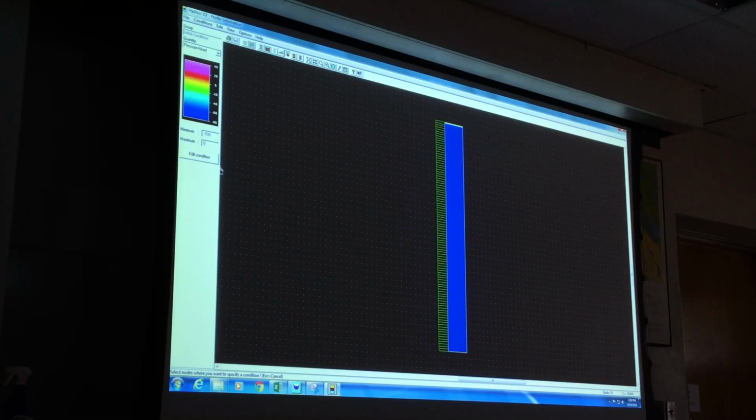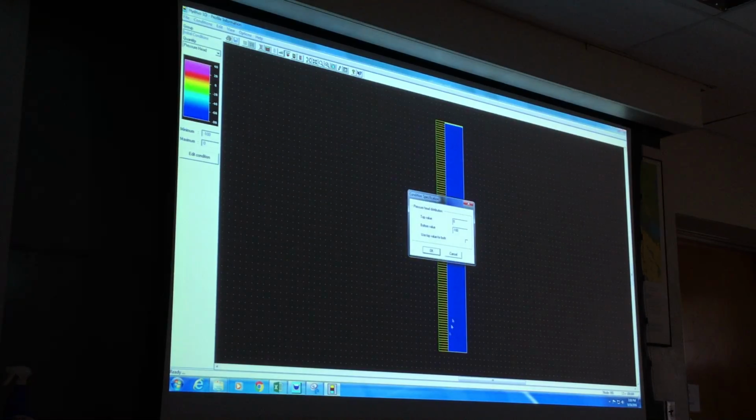The first thing, we want to change everything uniformly to minus 330 centimeter. Minus 330 centimeter is often associated with field capacity. This is the matrix potential after internal drainage. If you wet up the soil and you have internal redistribution, then we usually assume approximately minus 330 centimeter.